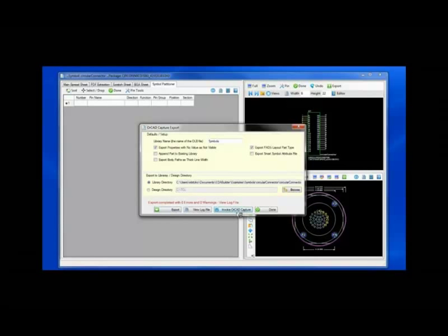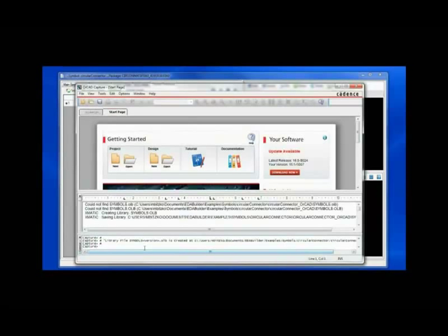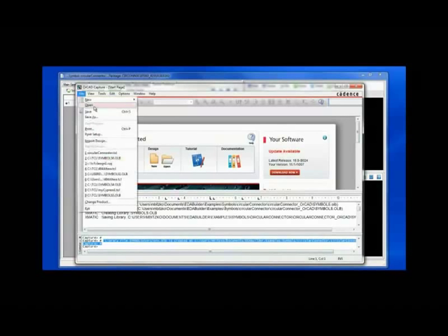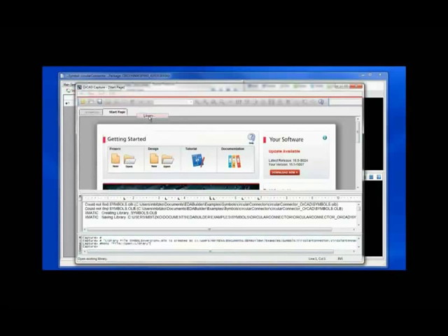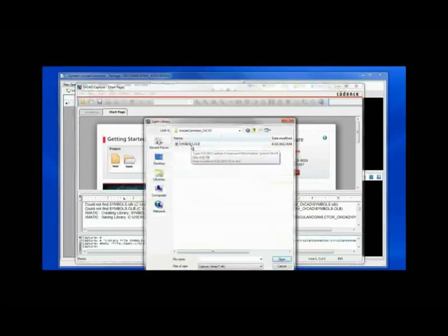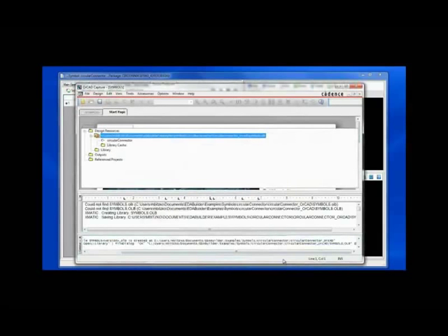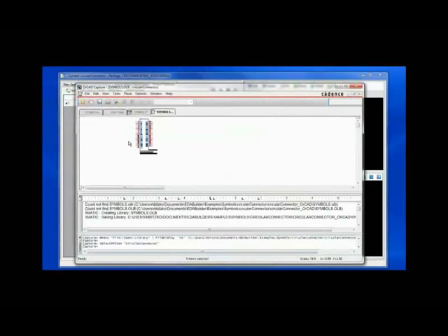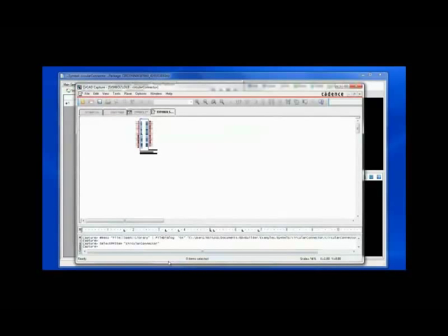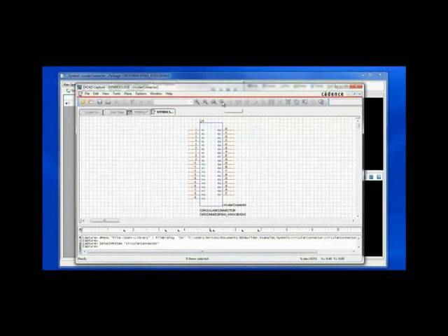Let's invoke OrCAD Capture. We will import the model directly into OrCAD Capture. I will now open up the library, the OLB file, and view the part, completed part with its integration to the PCB footprint land pattern model with the pack type modeling.